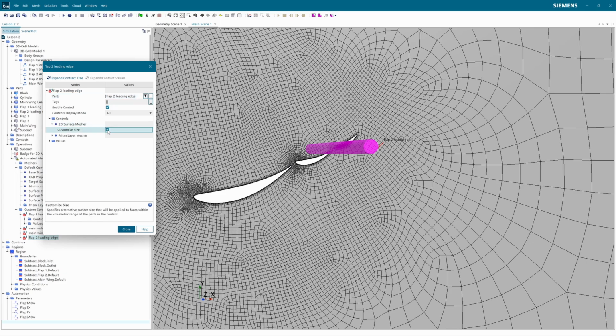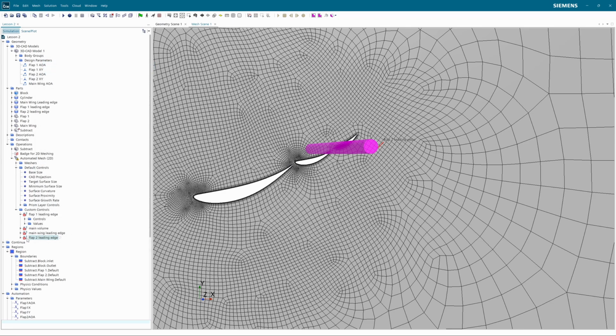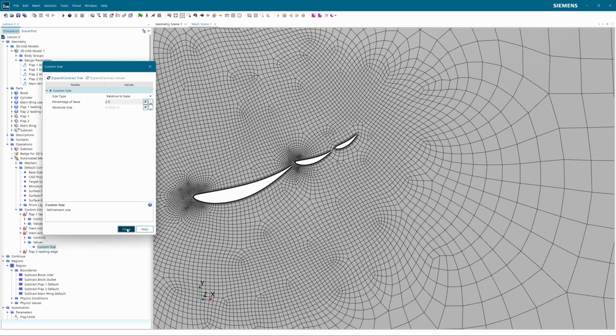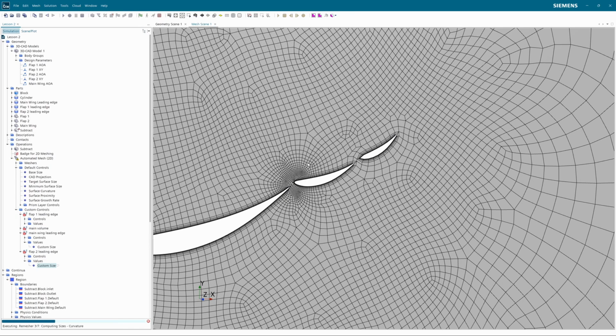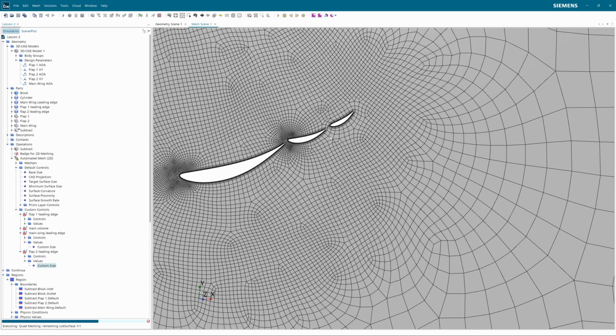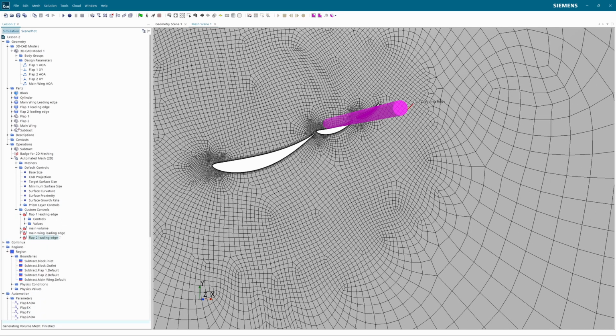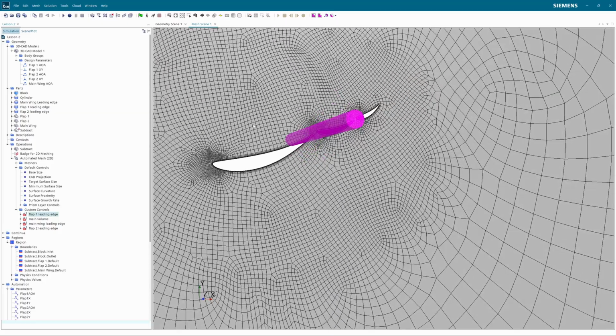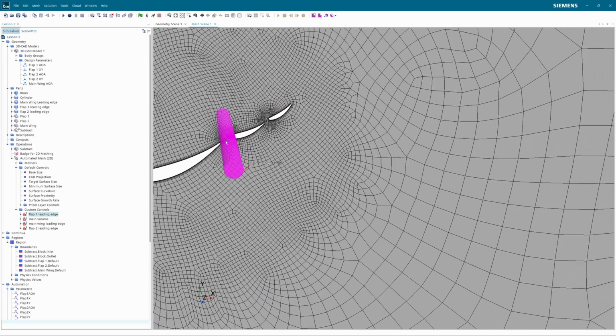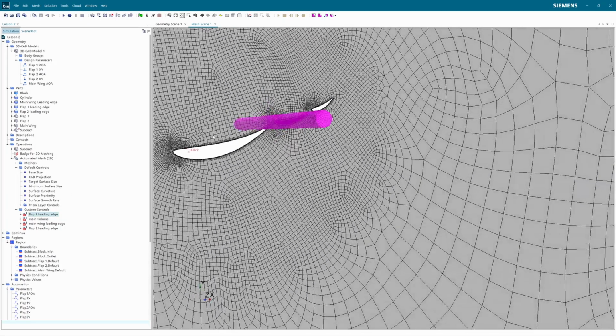And we're going to make sure that we can customize the size further of these cells. I'm just going to check what value I used, 2.5. So value up, 2.5. And all right, as we have done this right now, when I remesh, there is increased detail around this zone. And the nice thing is that, because you've created these all apart, of course, you only saw me create this one, but the main wing one is easier, as there's no movement, so no parametrization. And the leading flap 1 has a less complex formula, so just remove the parts where you add these lengths, and you will come to the same conclusion.